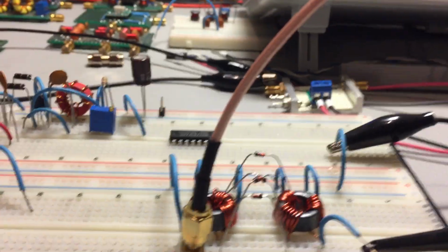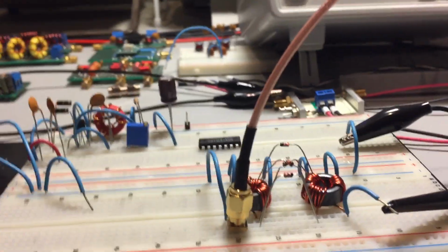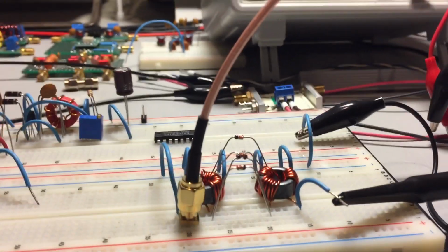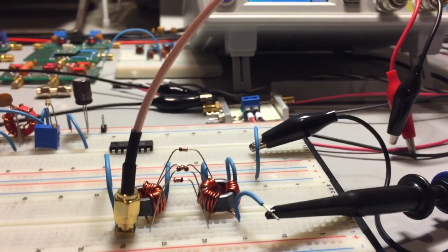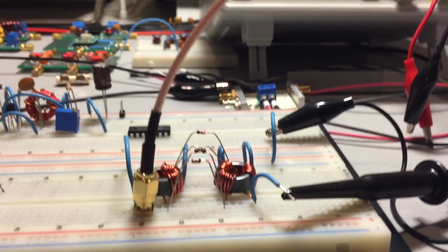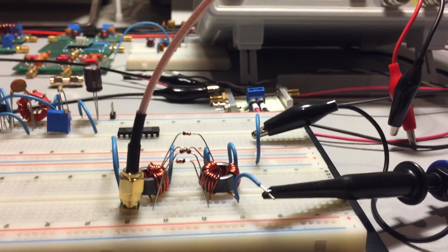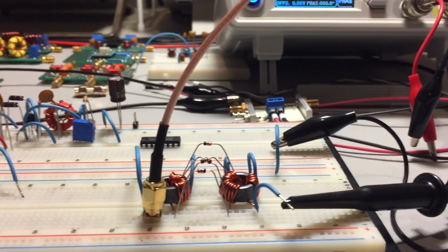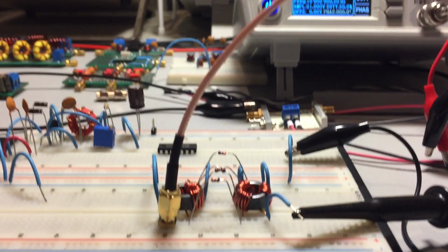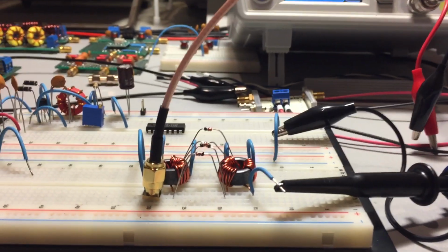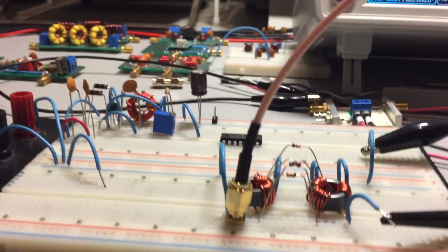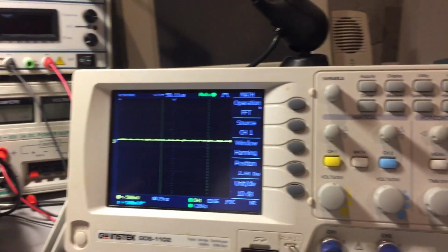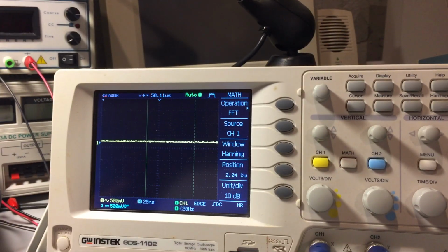Now this is a breadboard, so this is going to be limited to just the high frequency. I'm going to try to get it up to 30, maybe 40 megahertz. If you build it on a perforated board, you'll find that the performance is much better without all the lead lengths and jumper wires and effects of the breadboard. There's a lot of parasitics there. But I thought for this demonstration, I would just go ahead and breadboard it and see how it performs. So let's take a look at the waveforms on the scope.